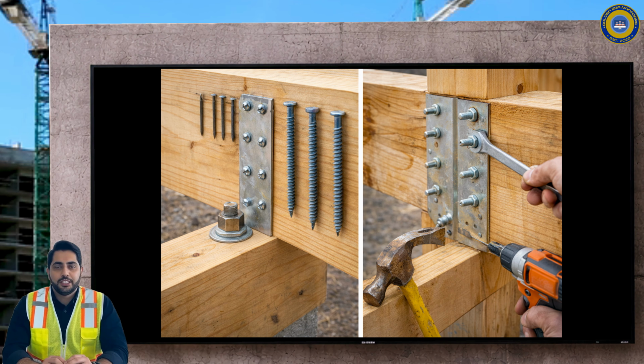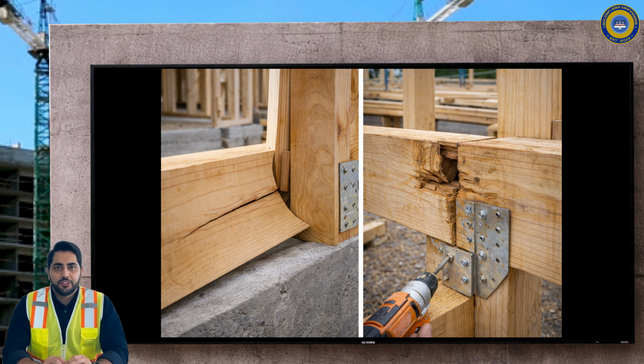But there's an important condition attached to all of this. Solid wood only works when builders understand what it will do, not what they wish it would do. It expands and contracts. It dries. It moves. And if those realities are ignored, the same advantages that make wood attractive can turn into long-term performance problems.